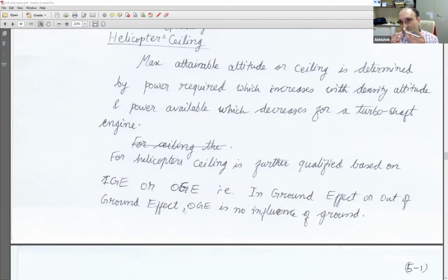Normally, when I keep increasing my angle of attack in a static scenario, I reach a point where the pressure gradient over the top surface increases so much that the flow separates and I get a static stall. But when I'm moving so fast, the flow separation depends on how fast I'm moving, because it depends on the history of what state my airfoil or wing was in at the previous time step or previous situation. So all those play a role.